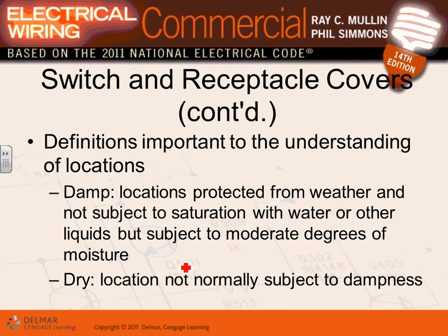Wow. Interesting. So because of all of this, guys, they used to put receptacles in the past outside. They're made from a material that can be affected by the heat and cool. And I did it many times. You go to change a receptacle, I know how many of you, and it falls right in your hands. Anybody have done that? Falls right into your hand. So they're now making it more robust to handle the heat and the beating that happens from the sun. So what was it, 2008, I believe, they started requiring all your receptacles to be weather resistant in damp and wet location.